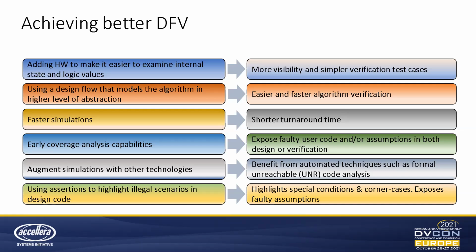In each slave, on its base address, you put a register, which is an ID register, a unique number representing the type of module and some revision number, for example.